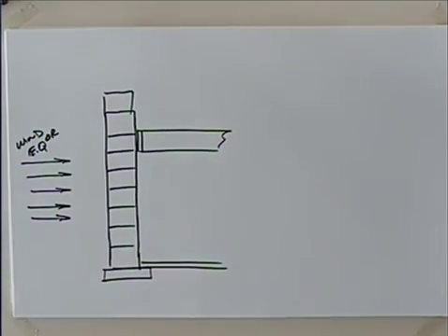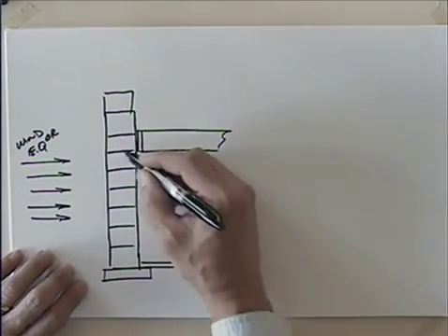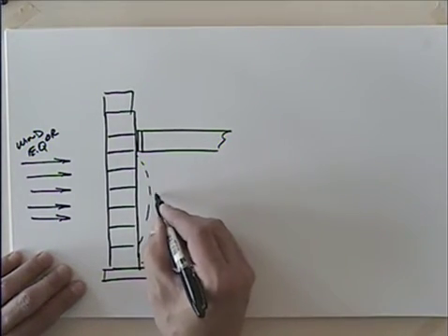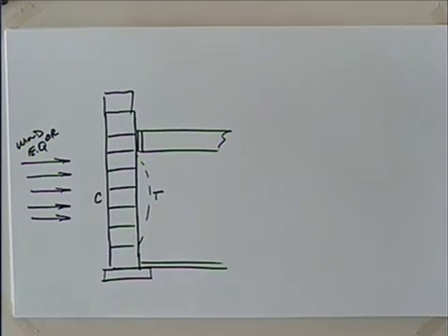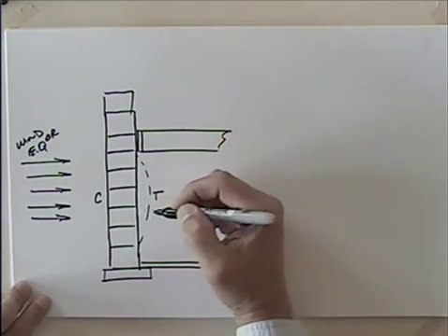So you've got wind or earthquake there, and maybe that's trying to deform the wall this way, right? So we're going to end up in this wall with tension on this side and compression on that side. So we go downtown, we look at a masonry wall that stood there faithfully for 70 years. Does it handle compression well? Yeah, pretty well. How about tension? Yeah, not so good on the tension, right? So you end up with a lot of tension stresses here that you don't want.